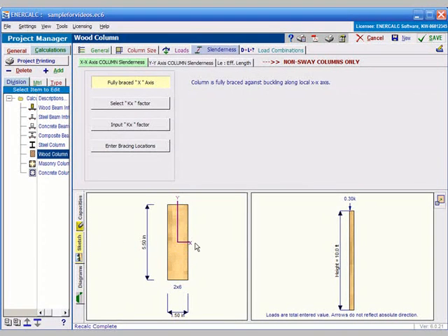X-axis refers to this axis where if the buckling is occurring, it's going to occur because of movement of the column along the x-axis laterally, whether by failure in bending, moving along the x-axis this way, or for column buckling, moving along the x-axis. And so for this member, you obviously need greater bracing along the x-axis because it's so slender. Along the y-axis it isn't so great.